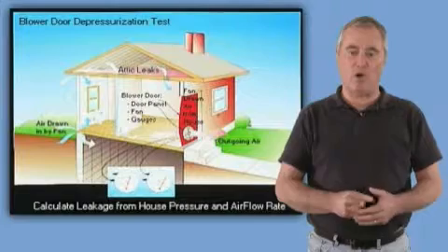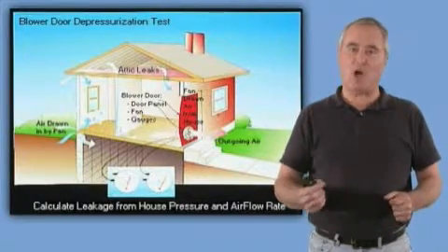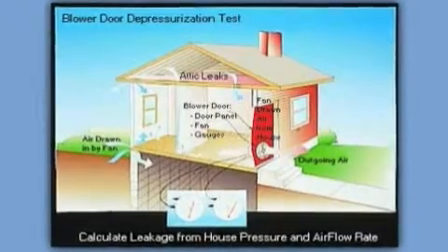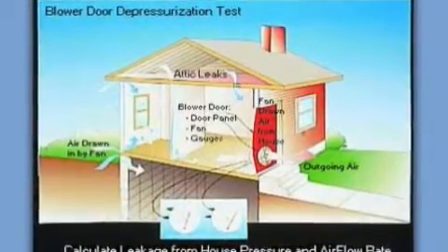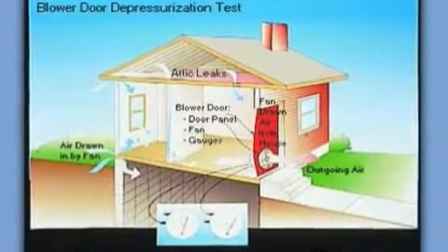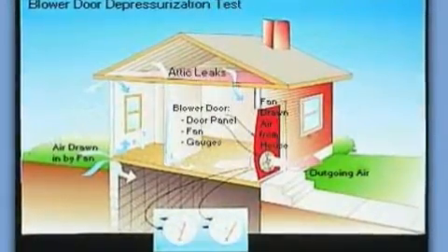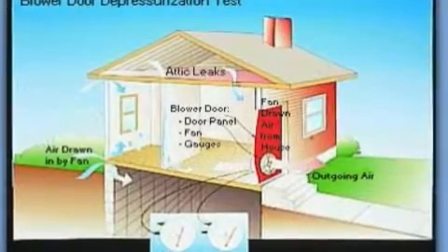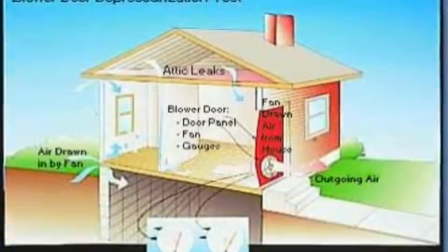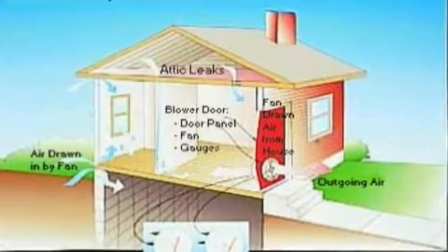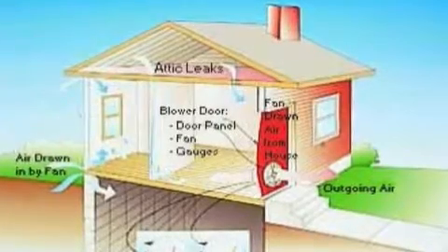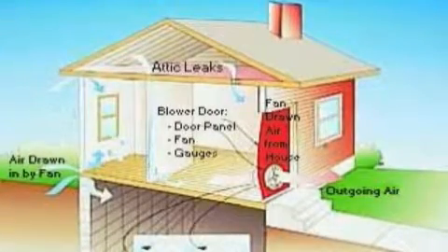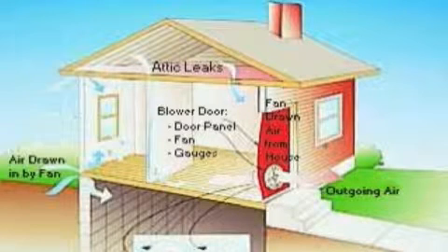In this sketch, we show the blower door discharging a bunch of air, blowing air out of the house, and we show that there's several locations through the ceiling, through the rim joist, out of the basement, through interior partition walls, where air leaks back into the house to replace that air that we've exhausted with the blower door. Our goal is to use the blower door to guide us as we seal the air leaks in our house. We want to make constant progress, a constant reduction in the leakage amount as we work through our sealing process.